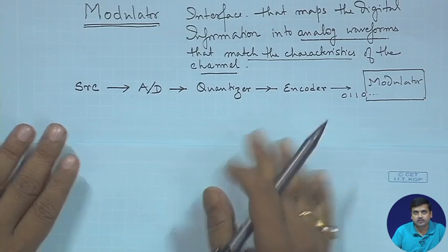So, before we move further, we would like to spend a little more time on this, trying to see why it is like this. If we say that there is a channel which allows you to carry forward the signal in a coherent manner, then you could take up schemes, for example amplitude modulations, right. Whereas if it says that it will not restore the phase as it goes through, then you could think of intensity modulations, right. And there could be channels which could say that in some frequencies the amplitude would be attenuated, whereas in some frequencies the amplitude would be amplified. So, then you can think of modulations which would be almost resilient to amplitude fluctuations, for example let us say phase modulation or frequency modulation and things like that.